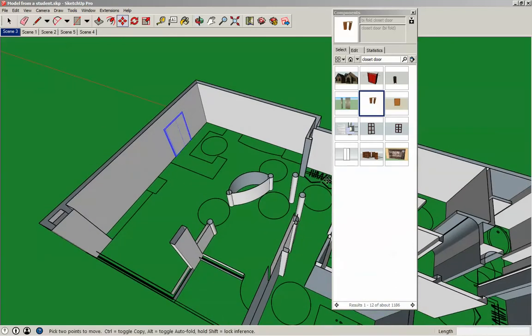And the way you can do that, like let's say I wanted to just put a window opening in here. I don't want to put a whole window component. You have to select the existing model. So I'm going to use my select command, and you can click on the select button, or you can hit the space bar. And I often have my extra hand, my third hand, on the keyboard ready to hit some of these keyboard shortcuts. M for move, P for push pull.